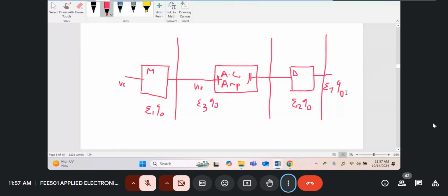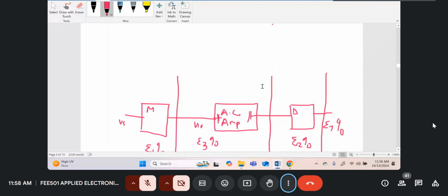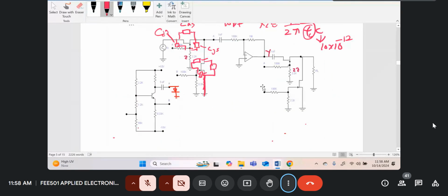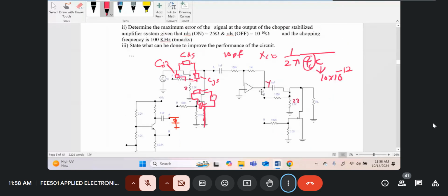And you can compare it with the error which would have been generated if there's no AC amplifier. So for example, supposing in this circuit over here the capacitor was not there, we just had a direct short. So this just becomes a normal inverting amplifier.